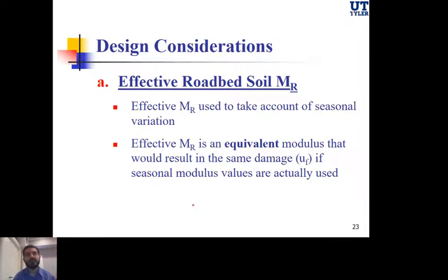The question here is whether you're going to do a resilient modulus test itself or a CBR or R value test. We need to understand that the resilient modulus, or the modulus of the soil, would vary by season. In a wet condition, if it's rainy, the soil will be very weak because it's very moist. If it's in the middle of the summer, the water will evaporate with time. It's going to start to gain some strength. And in some locations in the middle of the winter, when it's freezing, the water will be frozen inside the soil and it's going to pump up the overall strength of the soil.